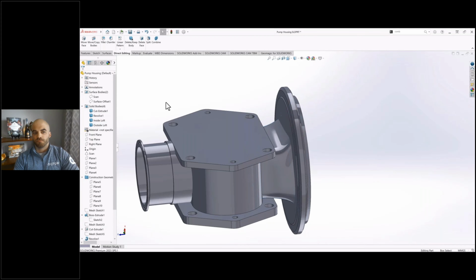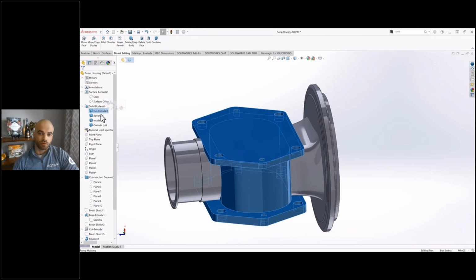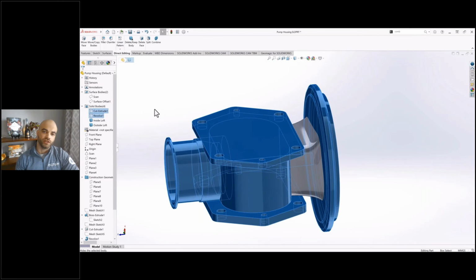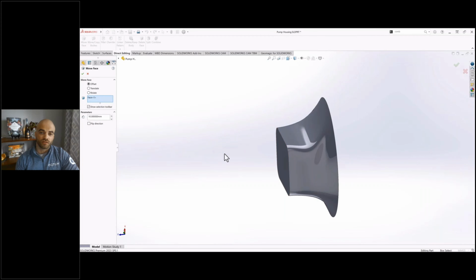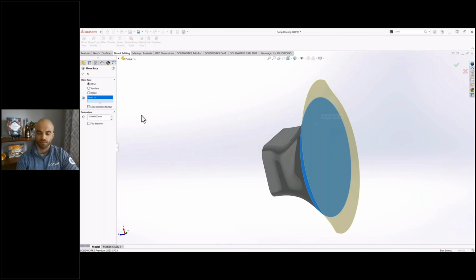It's double the work, right? It's 3 more sketch profiles minimum and a whole other loft feature on something that maybe is an as-cast surface. So maybe if it's not exactly like the inside surface, it just has to have a thickness and it's there. The inside surface is much more critical to the application. The outside surface is just providing a thickness to the body to withstand the forces of the application.